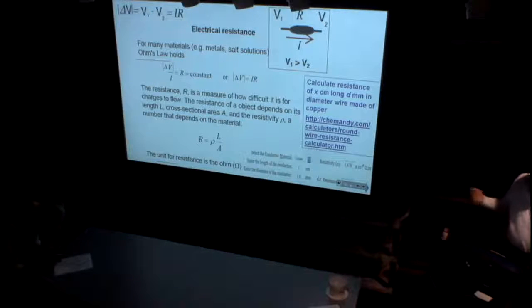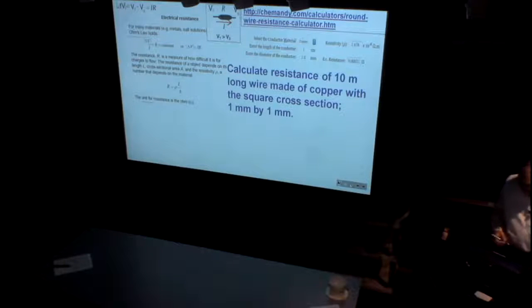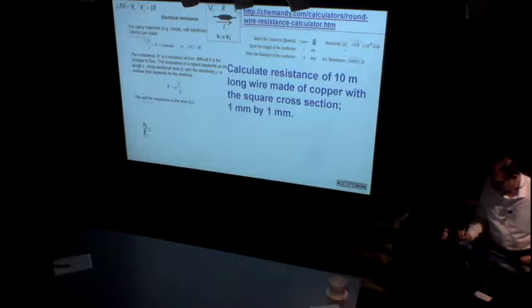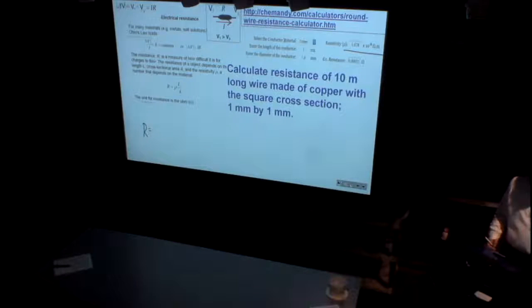And let's do one example related to calculating a resistance, in this case the resistance of a wire made of copper. All we have to do is practice using scientific notation numbers to calculate the resistance. Copper, what does it mean? It means we go online and search for the resistivity of this material. The only tricky part might be the unit. This is ohms times the meter, a standard unit of the international system of units, but very often it would be millimeters and micro ohms or something. Here we just have to use this number, 1.678 times 10 to the negative 8. This is the first number, the resistivity.